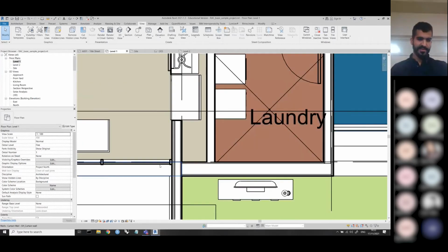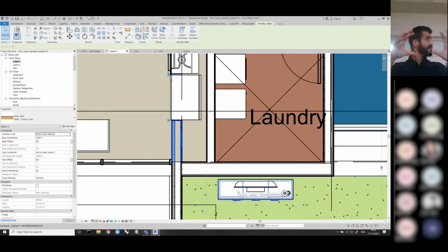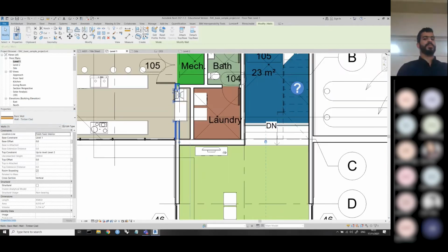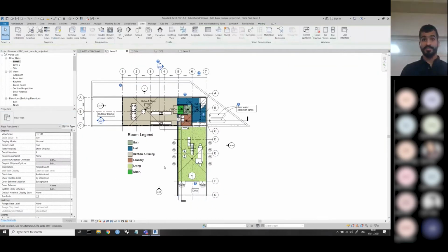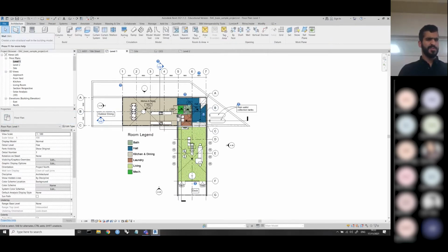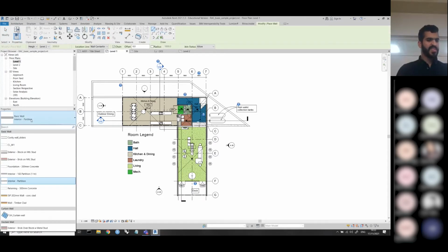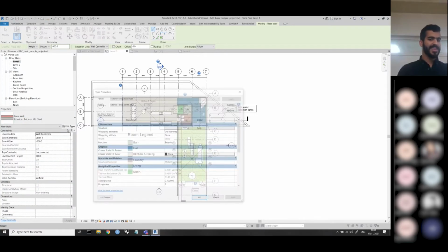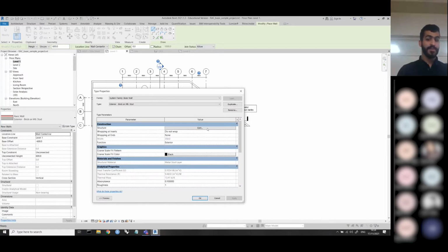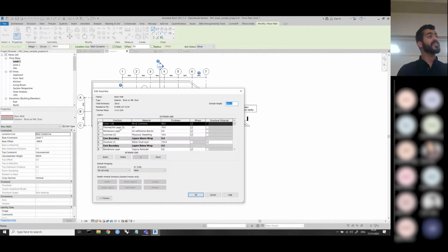But you see, when you click on these, this is one single model embedded with these different layers. In your own projects, you'll have different wall makeups. You're not all going to use the ones in Revit. When you make a new wall, you click on wall. This gives you some preloaded values, so it gives you a cavity wall, an exterior wall, and if you click on these and go on edit type, and then on structure, it tells you exactly what the layers are.